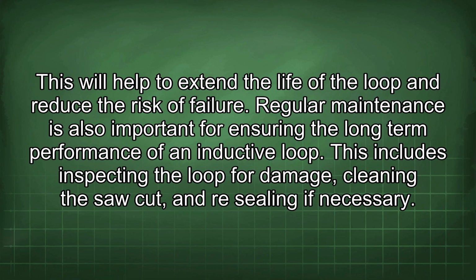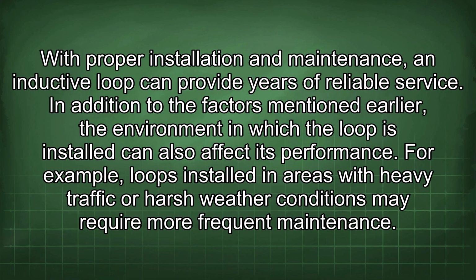Regular maintenance is also important for ensuring the long-term performance of an inductive loop. This includes inspecting the loop for damage, cleaning the saw cut, and resealing if necessary. With proper installation and maintenance, an inductive loop can provide years of reliable service.